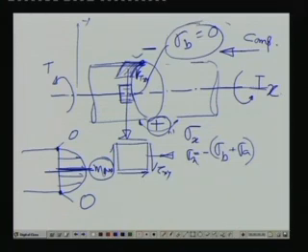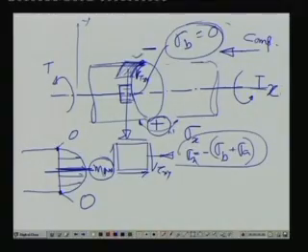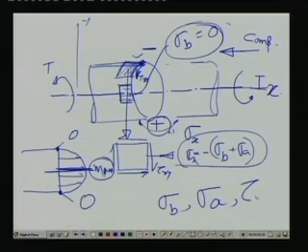So, normally what happens is that onto the shaft, the effect of the bending stress comes out to be relatively quite large. Okay. So, that is the reason it is a standard idea that you consider sigma bending, you consider sigma axial, and you consider shear stress tau, which comes due to the torsion.